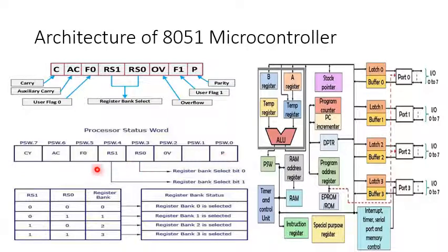The control flags are F0, RS1 and RS0. Let us first discuss F0. It is a user defined flag. The user defines the function of this flag. The user can set, reset, clear this flag through software.